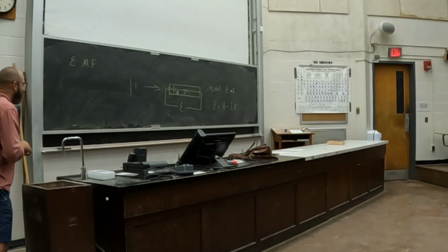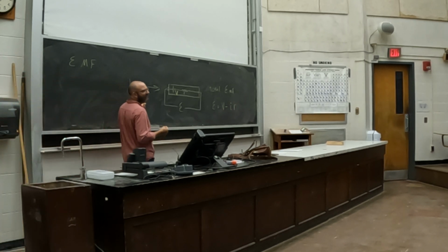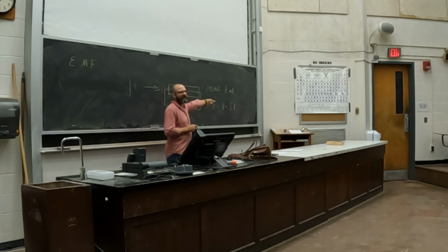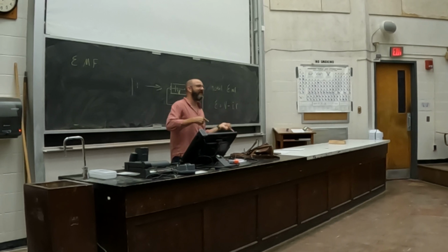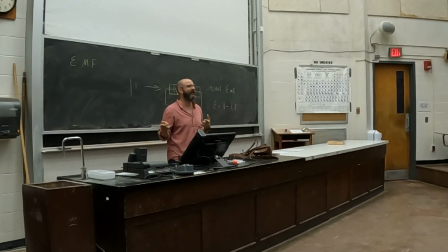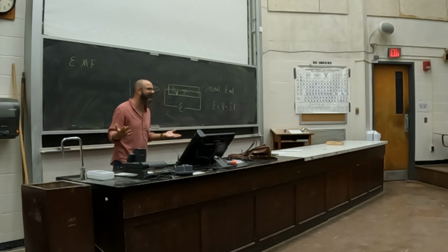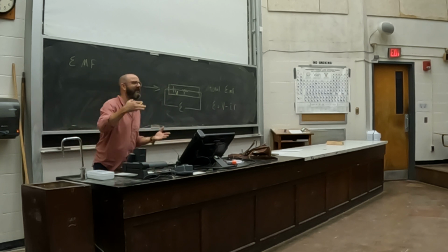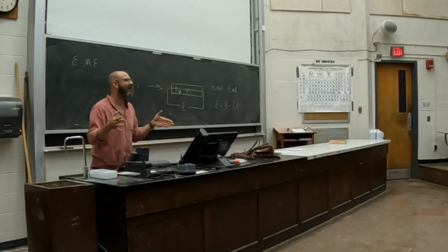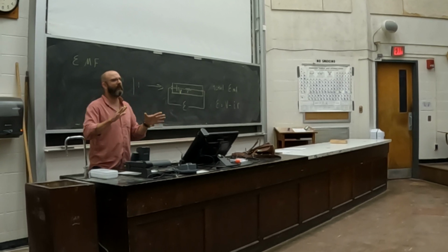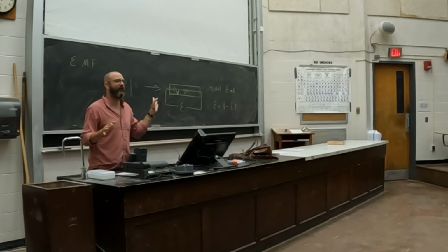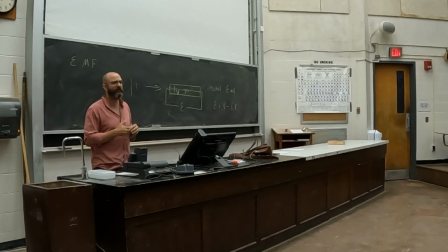That's because it's not just that the voltage is changing, the current is changing because the resistance is changing. It changes with the age of the battery. If you have a rechargeable battery, it changes based on how many times you charge it. It has a characteristic called hysteresis, which means it doesn't actually get back to the same physical parameters after you charge it that it had before you charged it. Even aside from the charging, the chemical structure is different in a battery after you charge it.